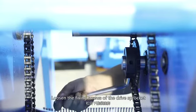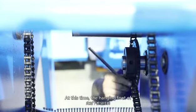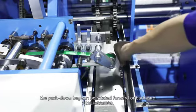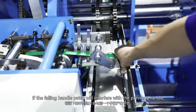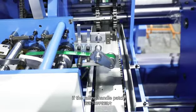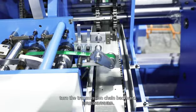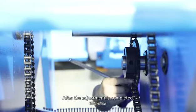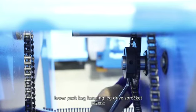Loosen the fixing screws of the drive sprocket of the lower pushing back hanging leg. At this time, the hanging foot of the push-down back can be rotated forward or backward. If the falling handle patch will interfere with the previous handle, then rotate the transmission chain forward. If the falling handle patch will be interfered with by the push-down back hanging foot, turn the transmission chain backward. After the adjustment is completed, tighten the fixing screws of the lower pushback hanging leg drive sprocket.